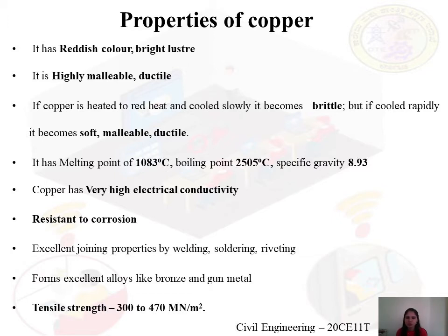The only problem with copper is that copper alloys generally cannot be strengthened by heat treatment. By heating, copper cannot be strengthened. Therefore, copper is used for cold working, and solid solution strengthening is done to improve the strength of copper. Hope you have understood the properties of copper.